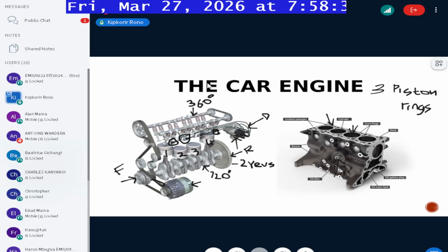The air filter can be changed at any time, and does not need to be changed when the oil is being changed. It's a common misconception in the industry. Because if, for example, you're operating in a very, very dusty environment, maybe you're always operating off-road, or maybe you're using your diesel generator in a place where there's always a lot of dust and dust particles, then the air filter can be changed as frequently as is needed. It does not need to wait, for example, 5,000 kilometers for the oil to be changed so that the air filter is changed. They have no relationship at all.